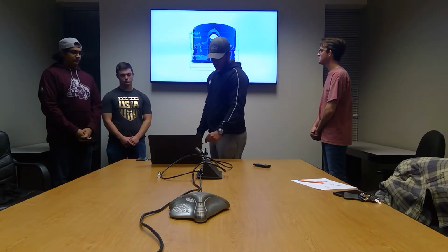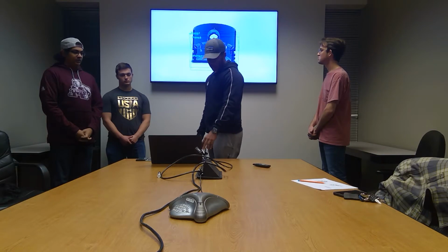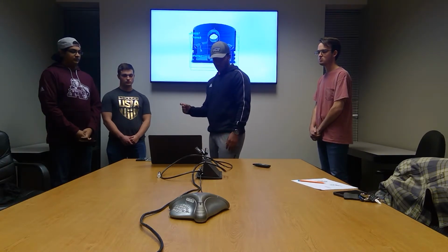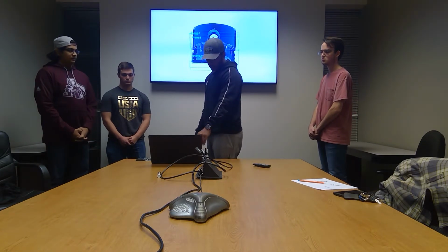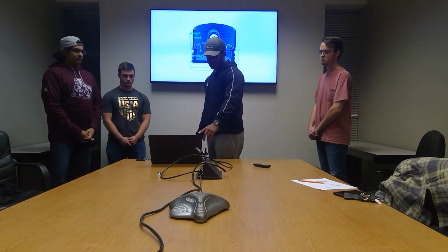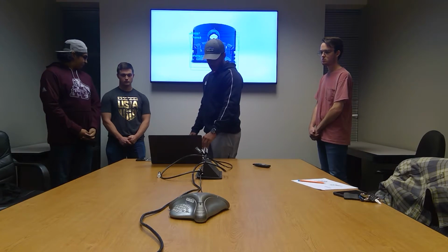Those areas that you see that are cut into the circles are not straight areas, they're on angles, so I had to find those angles by indirectly solving the distances between each other. And then at the bottom of those surfaces, you see this is a little on the angle, so I had to measure the depth from the top of the cylinder to the bottom of that area to find the area.